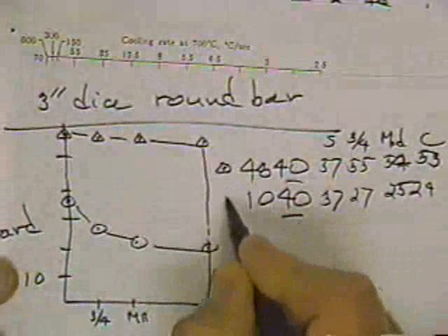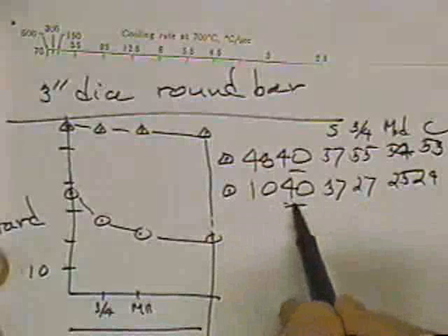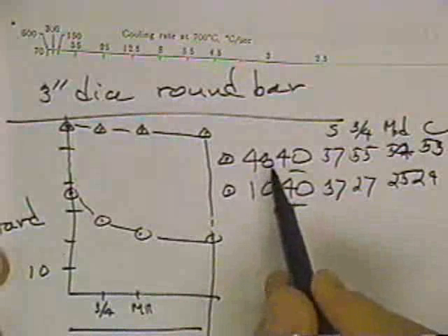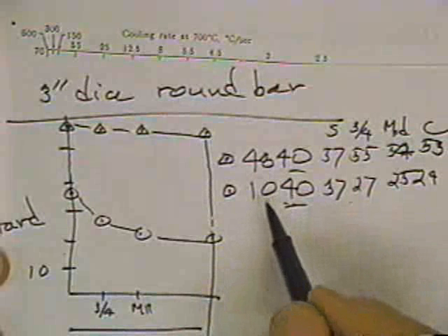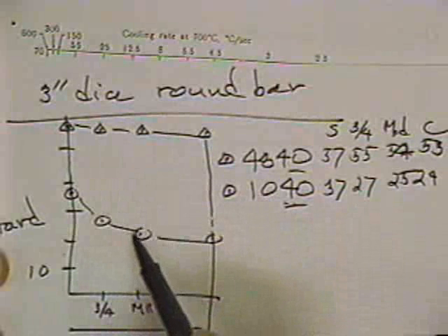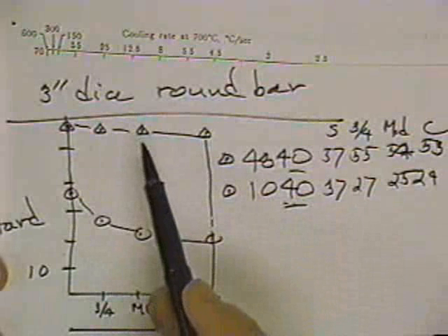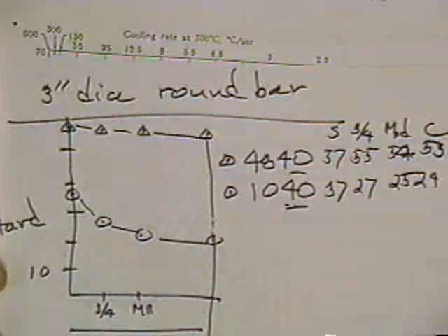And this shows you the effect of alloying elements. Same carbon. This has nickel chrome moly. It's a chrome moly nickel steel, and this has a little bit of manganese. So there's a huge difference in the hardenability. So if you wanted a fully hardened bar, you'd want to choose some alloy steel, not a 1040 steel. So that's how you can use the geometry data and that hardenability data to help yourself make predictions.